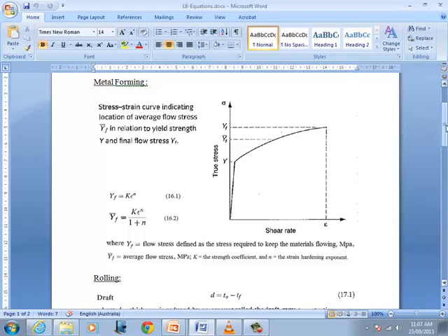What explains the behavior of the material when it is becoming harder and harder? It's different for different materials. They all become harder, however the magnitude of that is different. And this N is taking care of that. Depending on the type of the material, we've got different N values. For some materials it's greater, for some materials it is lower.